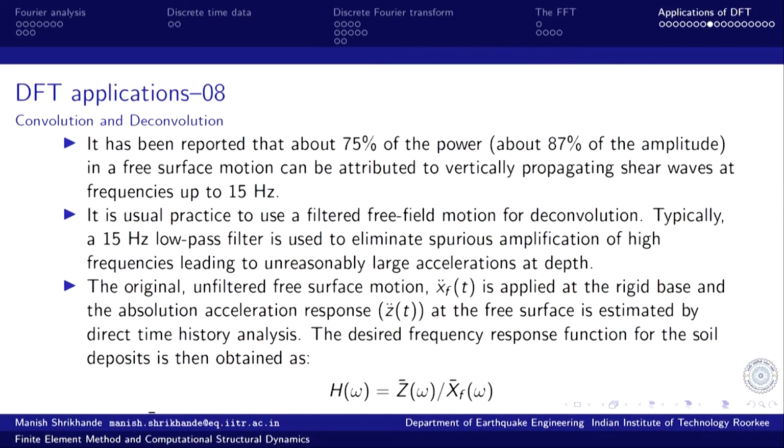So, the process that we adopt in deconvolution is that the original unfiltered free surface motion x double dot f is applied at the rigid base. We apply this recorded motion at the rigid base, and we can have a finite element plane strain model for the soil strata, develop the analytical model, and compute the response at the free field because of this input motion by using a time marching scheme, or even in the frequency domain.